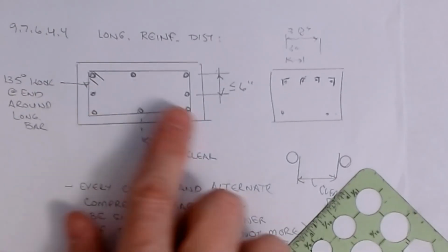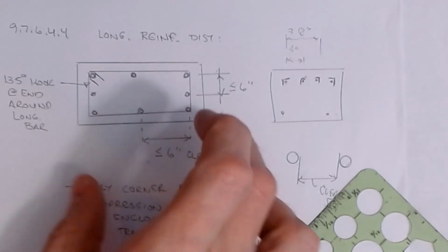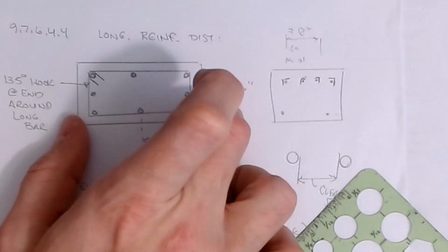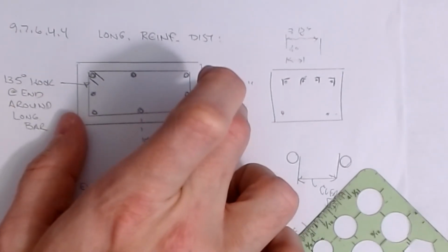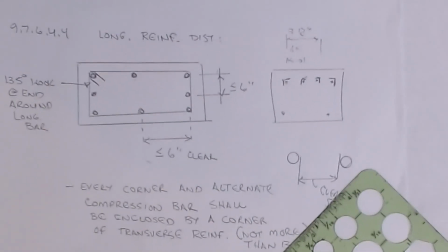So if you know because of the spacing I have to have at least 5 bars, well then when you do your AT calculation or your AL calculation for the face, you'll divide that number by 5 instead of by 2 like we would have done in flexure or in columns, if that makes any sense. So there's a lot of thoughts going into the details of this, so we've got to be careful and very mindful of that.